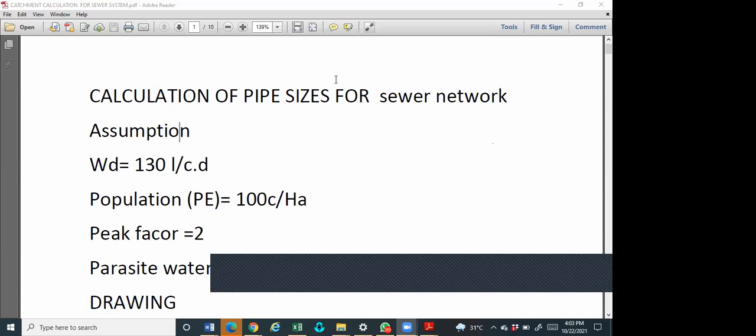So they chose 2.3. In those days, when somebody did something on water, somebody would come and tell them that the water demand for Abuja is 230. For me, as a water expert, I know that they were only multiplying the safety factor. But the real value that was used was 100 liters per capita per day. I can defend it anywhere.